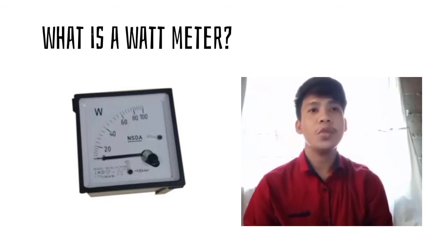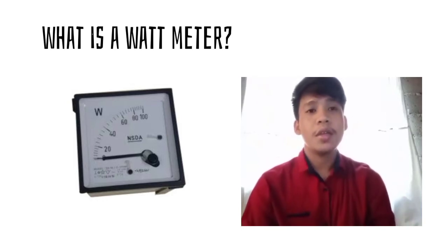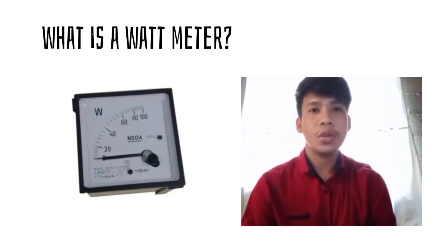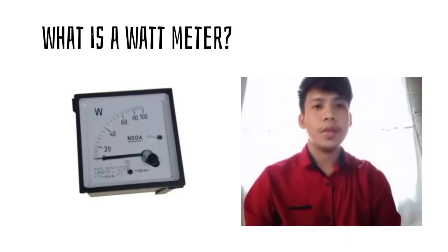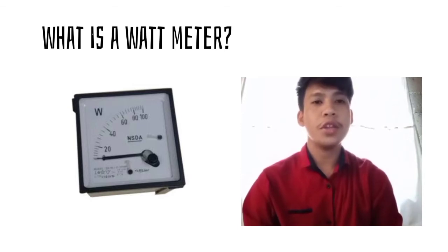A wattmeter is a very useful tool used by electricians and anyone in the electricity business to measure the amount of electricity being used. A wattmeter is an instrument which gives a visual indication of the amount of electrical energy being supplied to a circuit. There are two commonly used types of wattmeter. The analog ones are electrodynamic instruments and consist of three internal coils: two static current coils and a movable potential coil, which has an indicator needle attached to it.